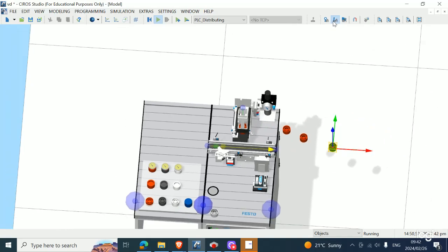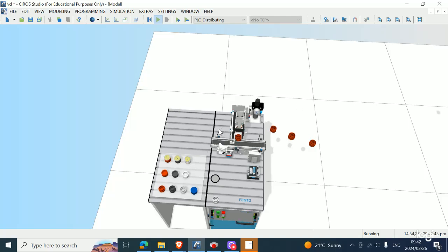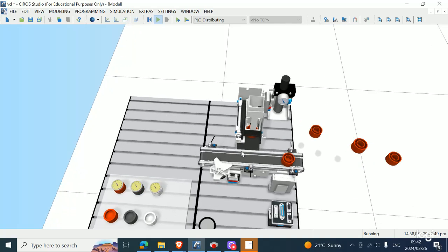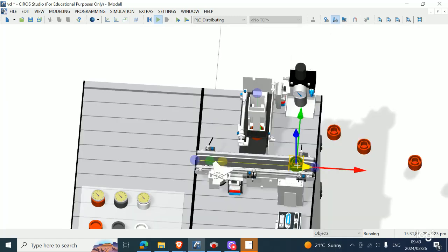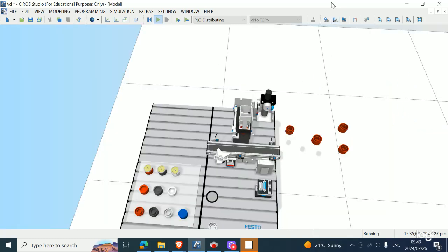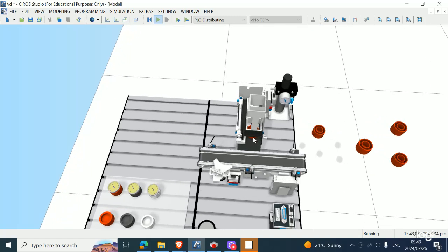So now, with regards to the cylinder ejecting a part, as you can see, the movement is almost too instantaneous, and it results in the other side of the cylinder interfering with the part in the roller. So what we want to do is delay input I1 by a certain amount of time before we let it actuate, to give the cylinder enough time to go back before the conveyor moves, so there's no interference between the two outputs. So we want to accomplish that task by using a timer to delay the activation of I1.